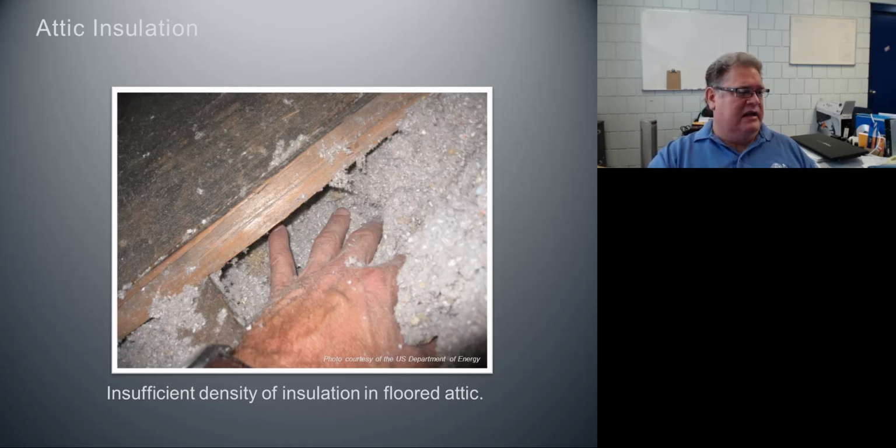Okay. Here, we were talking about this earlier. If you have a floored attic, you need to check the density underneath it. So our flooring is this area over here. This is our decking, and we're coming in under this this way. That's going under the floor. And you can see we don't have very much density under there at all around this guy's fingers. We're not seeing the proper density under that floor. So that's probably an area that's going to have to be addressed.